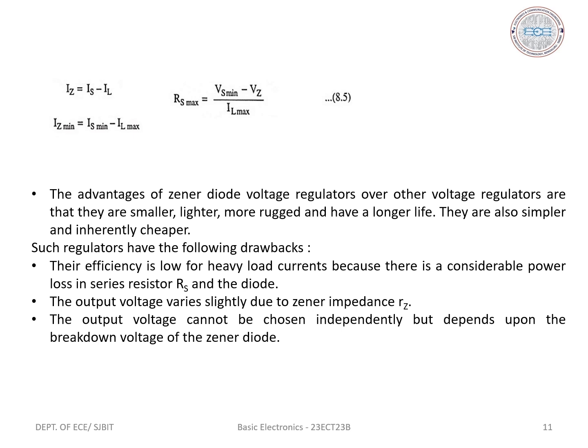Next, we will consider the Zener regulator with no load. When the reverse voltage applied to the Zener diode equals the breakdown voltage Vz, Zener breakdown occurs and Iz flows through it. When we apply KVL to the loop, Vi minus Iz into R1 minus Vz equals 0. That is, Iz equals Vi minus Vz by R1, or R1 equals Vi minus Vz by Iz.